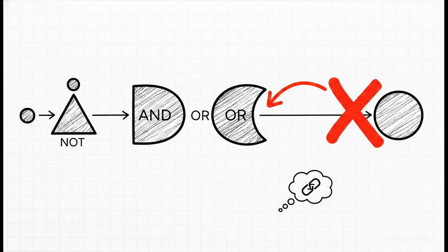SystemVerilog organizes behavior using specific always blocks. The first major one is the always_comb block. This is specifically designed to handle combinational logic securely. And combinational logic just means the output depends entirely on the current input right at that exact moment. It's like a math equation. By using always_comb, the software instantly knows your intent, which prevents accidental memory loops from forming in the silicon.